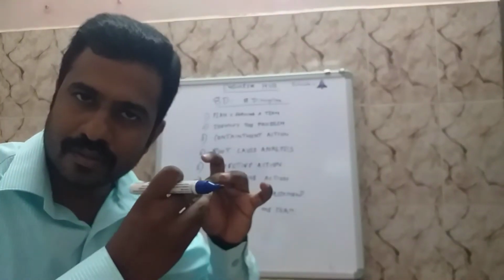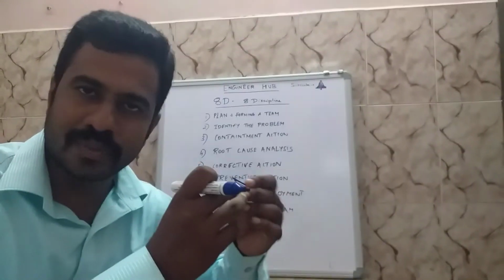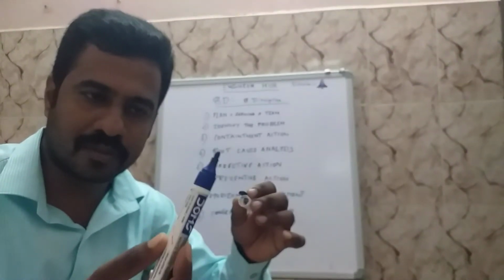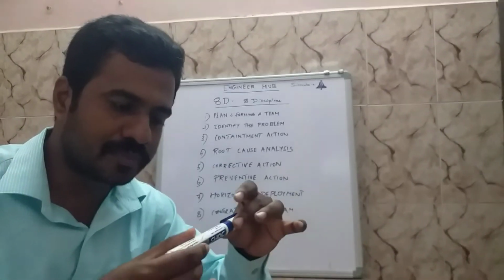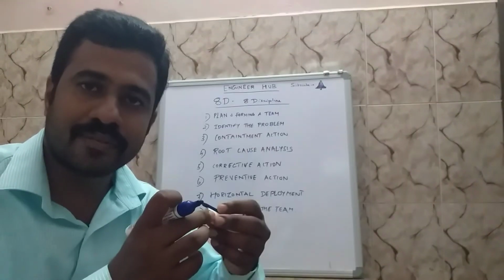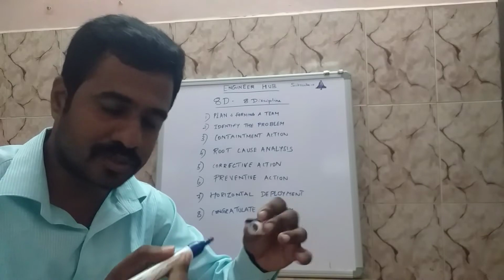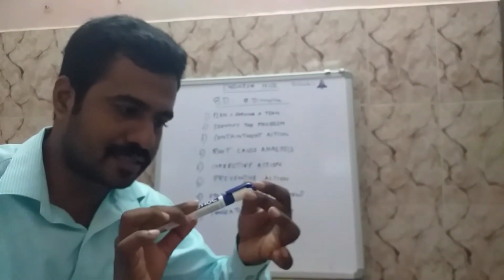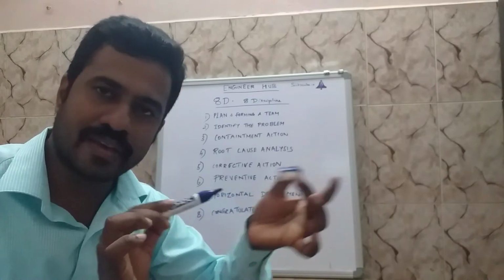The diameter of the cap is less. It should be 11 mm. The diameter should be 11 mm, and the other part should be less than that, almost 10.5, so that a perfect interference fit is there. But they have given about 10 mm regarding this. So what happened was, it does not go inside. It does not fit, it just loosened up. So we have a problem.